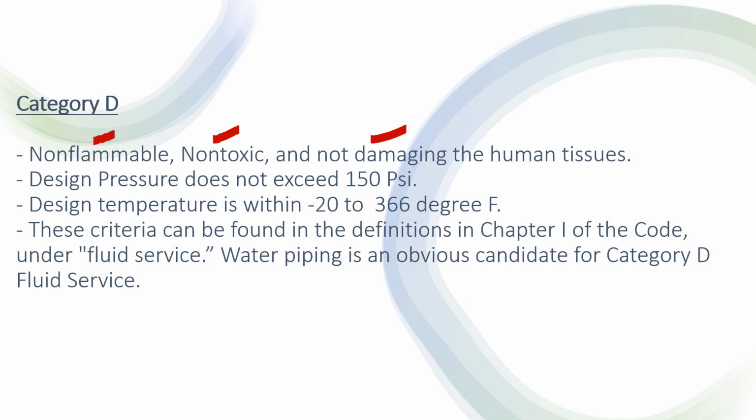Next, design pressure does not exceed 150 psi. Okay, almost 10 bar, 1 bar is 14.5 psi, so near about 10 bar. Design temperature is within -20 to 366 degree Fahrenheit. Okay, you can convert it to centigrade. This criteria can be found in the definition in chapter 1 of the code under fluid service.